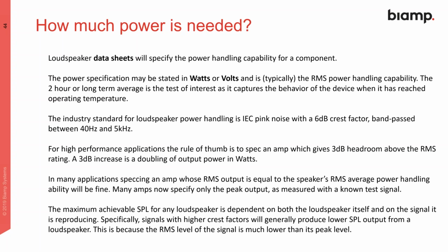When we look at the data sheets for speakers, they'll specify, as I said, in watts or volts, that RMS power handling capacity. Generally, they may give an instantaneous. They should give a long-term average for pro speakers. They'll also give an infinite duration test. We're not really interested in the infinite one. We want the average one. A lot of companies have done 2-hour windows, but what it allows it to do is heat up the loudspeaker's voice coil, get everything to where power compression starts to set in within the device.